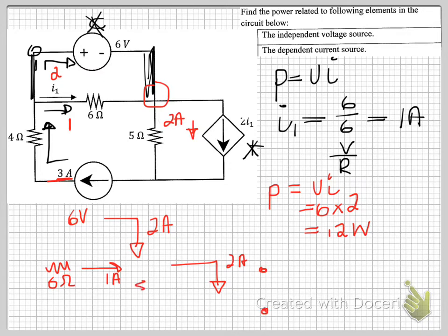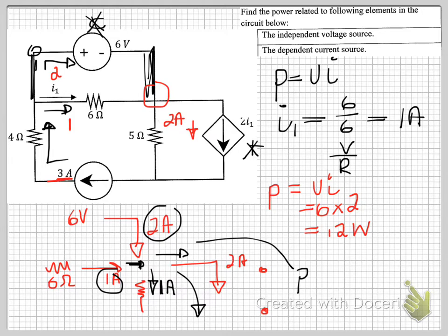And now we're asking ourselves how much current is going through this resistor here. By looking at this, we can see that it's a simple KCL. You've got 3 amps coming in and 2 amps leaving this way, so therefore 1 amp has to go down here. This is why 1 amp is going through our 5 ohm resistor, because 2 amps coming in there, 1 amp coming in here, so therefore 3 amps need to flow out between these 2 nodes, right?